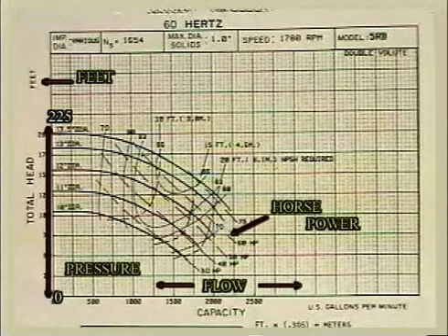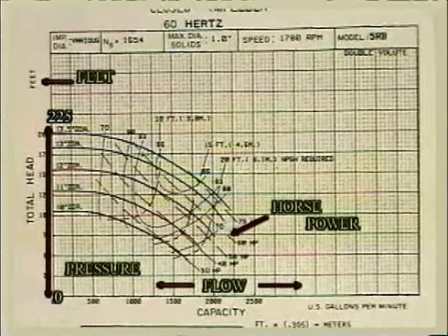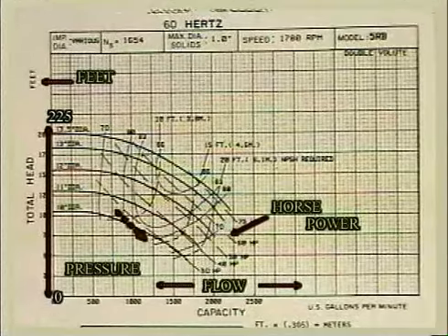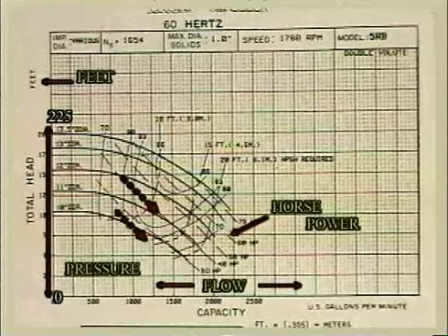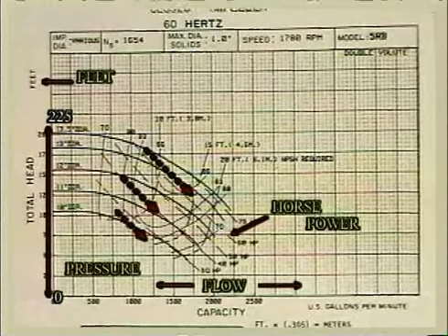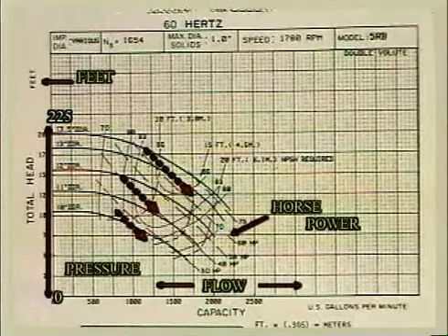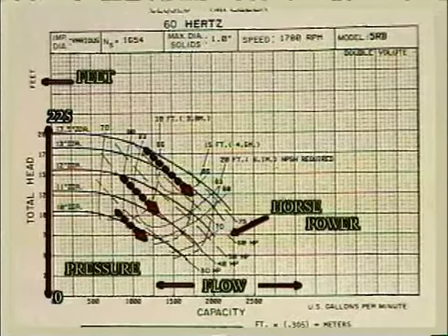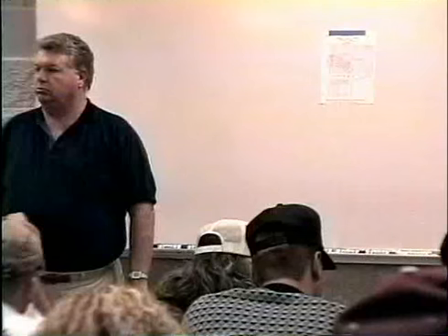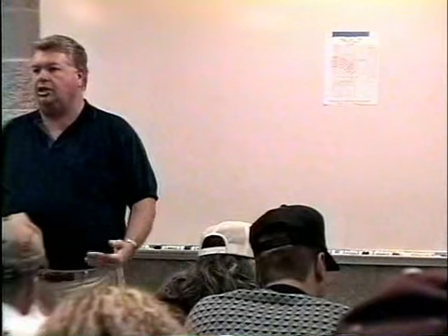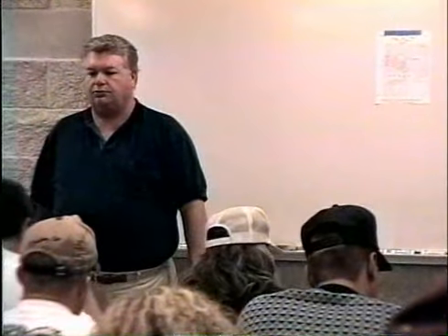Now horsepower. Horsepower is shown internally in the curves, and you can see there are the diagonal hash lines going from upper left to lower right across the face of the chart. And those diagonal lines give you the different horsepower ratings. Now see, the horsepower is going to vary according to pressure and flow. We could put all kinds of different motors on this particular pump.